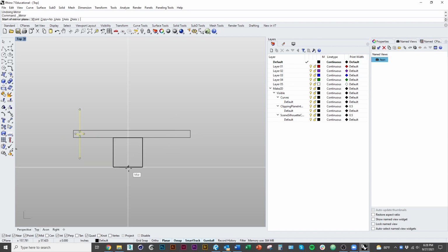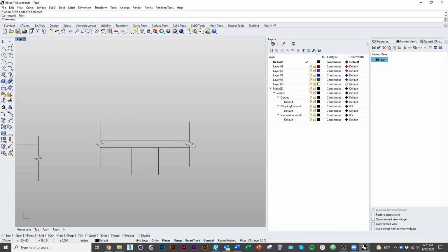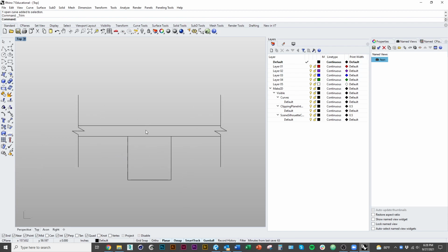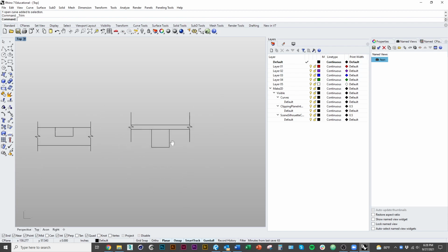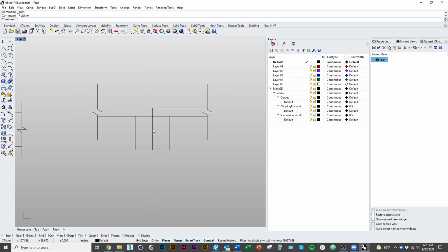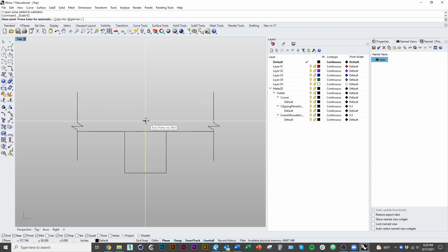Make sure that's, oops, copy it. Make sure that's evenly spaced. Okay, so select those and trim. So that's our seat. That's where we're cutting away because that continues and we don't need to see it. And then we would want to draw that bolt coming through, right? So first we'll draw the center line of the bolt. We would draw the real dimension of the bolt.